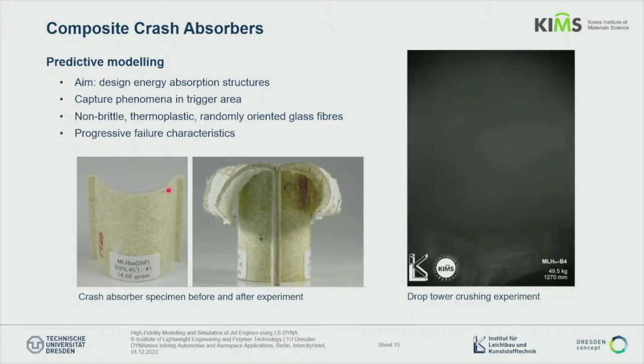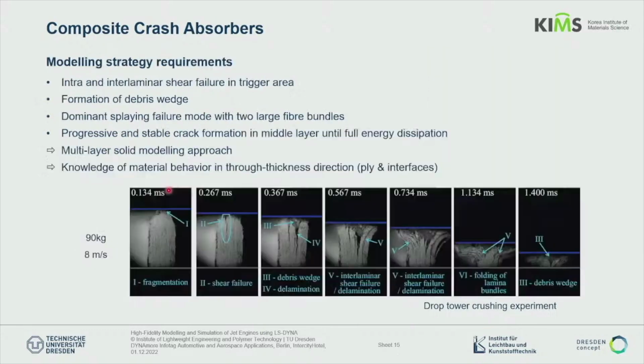That is the aim, but you definitely need to capture the phenomena happening within the trigger area, because this is governing the whole structural behavior. And of course, you need to somehow capture your failure behavior, your progressive damage behavior, or progressive failure behavior, delamination behavior during the impact process. So what have we done? We have firstly looked in quite a detail at what's really happening here, identified the relevant behavior, phenomena.